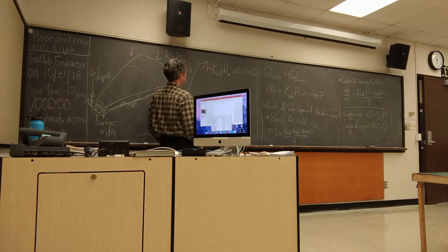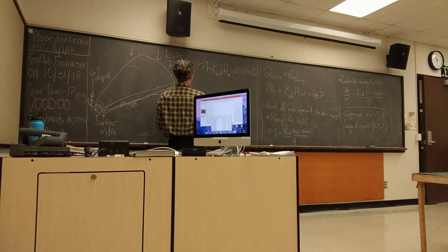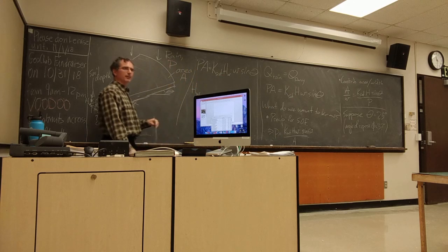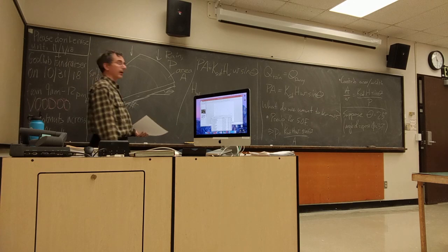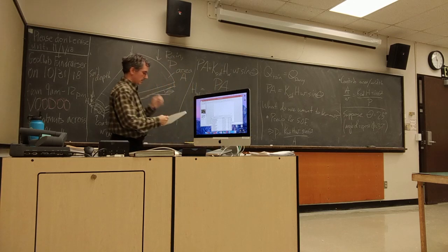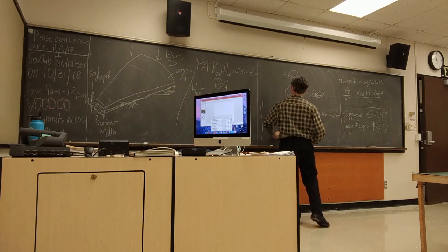So now let's say maybe I know the precipitation rate and so on. And H_W was something that was in my factor of safety equation, I might recall. So let's say, okay, we can solve for what H_W is if we divide both sides by k_sat W and sine theta. And then I can go to my factor of safety equation.